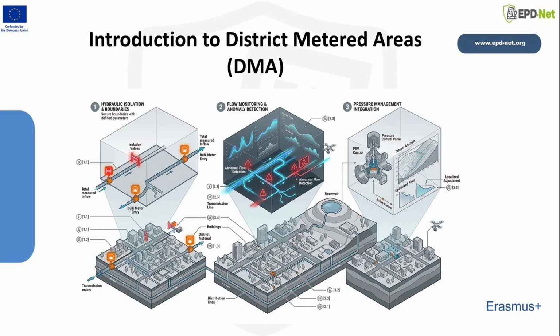DMAs are closely linked to pressure management. Localized pressure control within a DMA allows utilities to adjust pressure levels according to local conditions, reducing leakage and improving network performance. DMAs therefore provide a practical framework for implementing effective pressure management strategies.